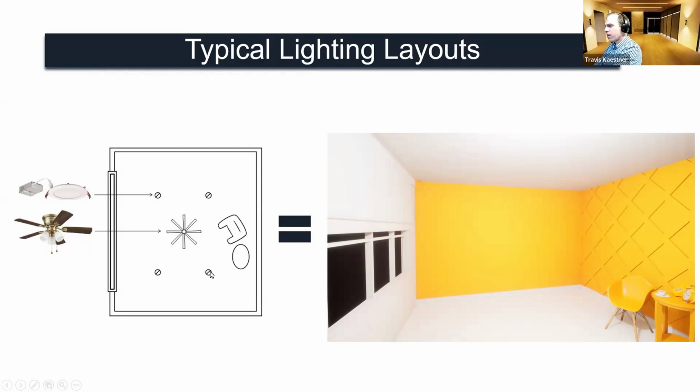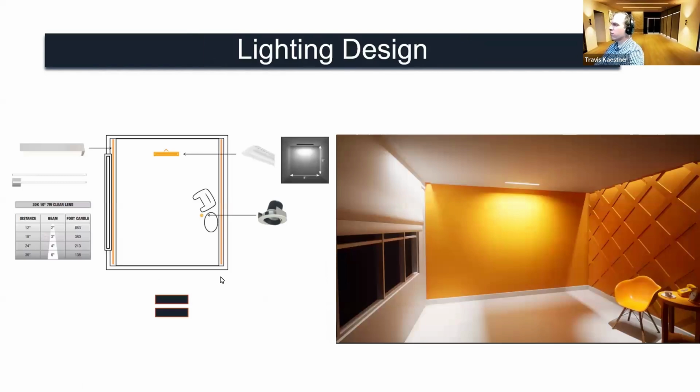Sometimes it's nice, but maybe there are other spaces that call for a little bit more attention, and that's where we do the layers of light. That's where it gets more specific, because sometimes it's not just the fixtures we specify, it's also speaking with the contractor and having them build a cloud or a drop ceiling so we can tuck in some little light bar slims or some narrow 30-degree optic linear tape lights that fit in there, and they're concealed so you're not seeing the light source itself.